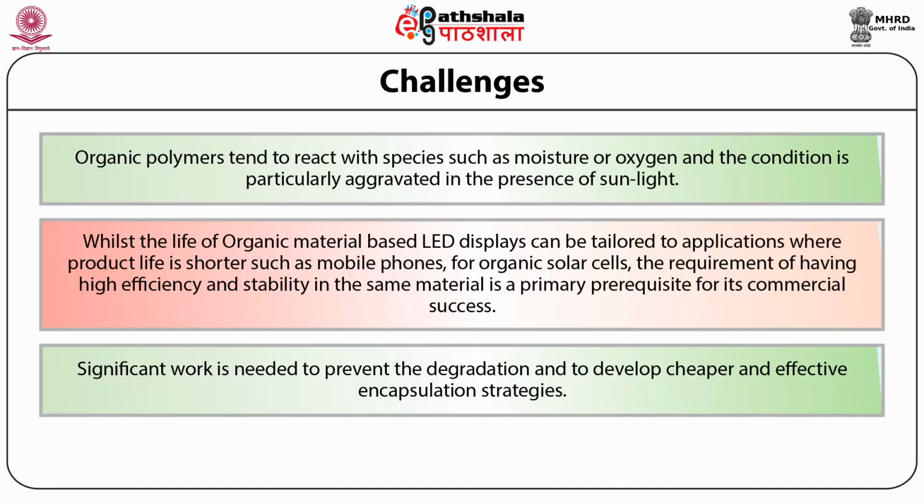Typically, intrinsic degradation implies degradation due to material alterations, such as changes in the morphological states of stacking layers and interface modifications due to inherent thermal characteristics of the active layer materials, while extrinsic degradation is typically triggered by external factors such as water, oxygen, and the type as well as the dose of radiation.